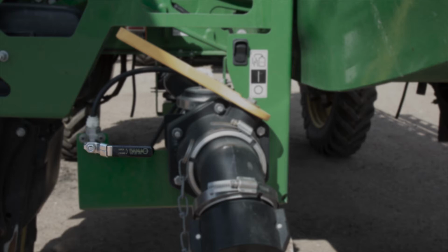Now when we load on the front fill, you notice there's a black switch just above that yellow handle. That switch opens and closes a valve in the sump of the spray tank. So if we're trying to load the sprayer, we first come over, we hook up, we open our yellow valve. We need to take that switch, if we're pushing on with a pump on the nurse trailer, and put that switch in the middle position, or that white line in the black box, the on position. That opens the valve, allows a free flow of product in when we're pushing it on.